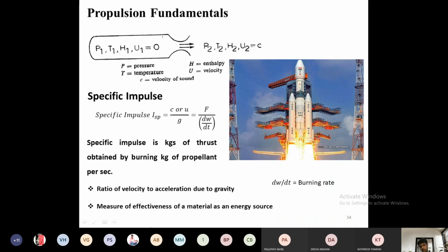For example, when a rocket has started from the ground, how can we assume that this rocket will reach the orbit within this time, or whether that fuel is enough to reach there? It is nothing but a mileage. In our general sense, it is nothing but a mileage: specific impulse. It is calculated only for propellants.